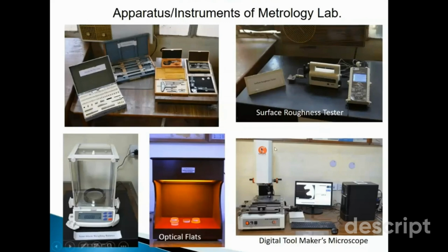This is a digital tool microscope. This is our measuring head, which has a very high resolution digital camera. It has a small micro probe which is used to measure dimensions in 3D. So it works like a 3D dimension measurement machine. A small gear is placed below the camera, and its image is acquired onto the screen. You see there, this is a gear profile, an involute gear profile.